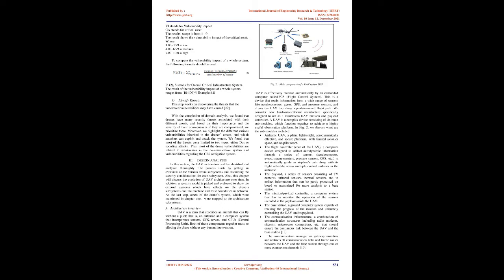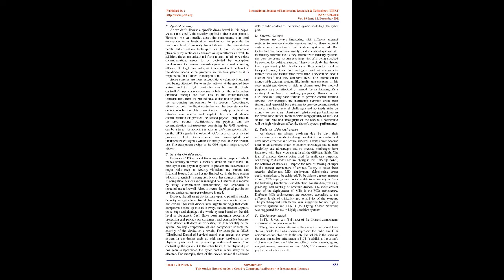The flight controller, core of the UAV, a computer device designed to collect aerodynamic information through a series of sensors, accelerometers, gyros, magnetometers, pressure sensors, GPS, etc., to automatically guide an airplane's path along with its flight schedule across multiple control surfaces in the airframe. The payload, a series of sensors consisting of TV cameras, infrared sensors, thermal sensors, etc. to collect information that can be partly processed on board or transmitted for more analysis to a base station. The mission/payload controller, a computer system that has to monitor the operation of the sensors included in the payload inside the UAV. The base station, a ground computer system capable of tracking the progress of the mission and ultimately controlling the UAV and its payload.